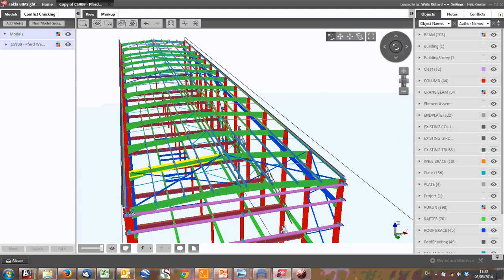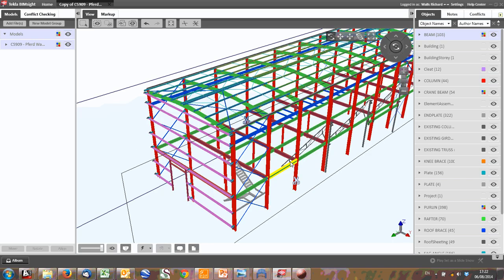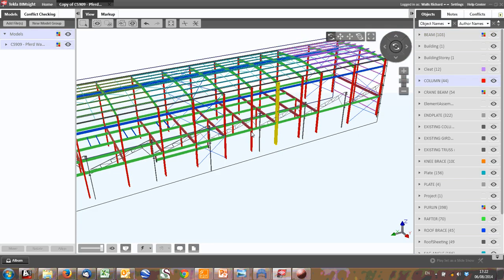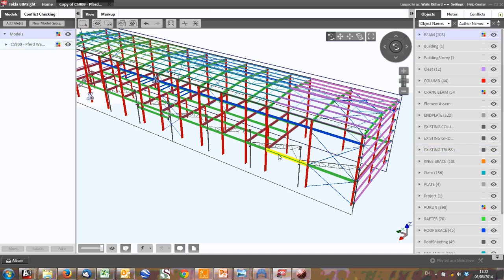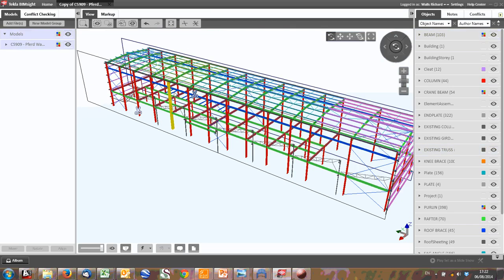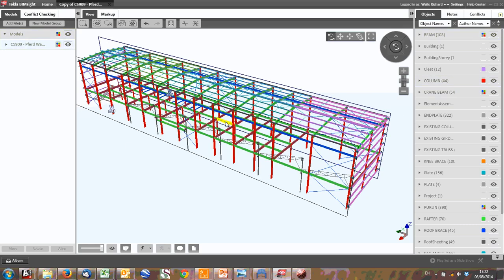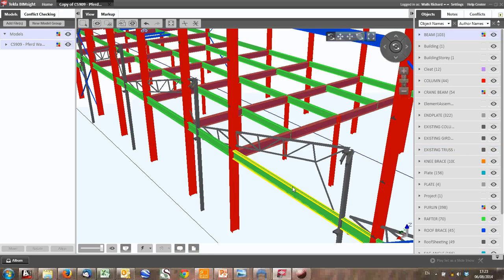Now, we can support this. Rather than designing each of these as a portal, why don't we just add in 1 or 2 braces and we can support this whole floor? Because this massive concrete slab that will cover all these beams is so stiff that it will act almost like a floor brace, like the roof brace.